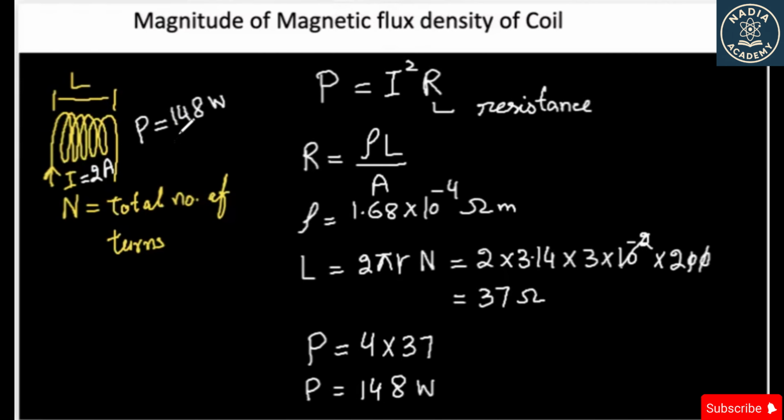And this is a quite significant amount of thermal energy. That could not be good for your coil. So you need to keep your coil at low temperature or in a water bath in this condition, or you need to redesign your coil. How you should redesign your coil is the project that you need to do. For example, you can increase the number of turns to reduce the current required to generate, let's say, a 0.1 Tesla magnetic field.